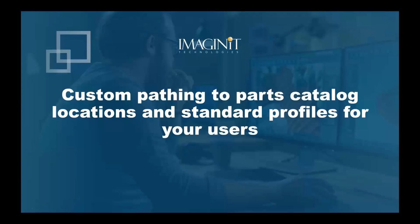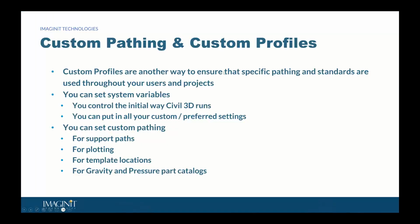All right, so now we're going to talk about custom pathing to part catalog locations and your standard profiles for your users. So custom pathing and custom profiles. Custom profiles are another way to ensure that specific pathing and standards are used throughout your users and projects. In the custom profile, i.e. an ARG file, you can set system variables, you control the way Civil 3D initially runs. You can put in all your custom preferred settings, all of your system variables, anything like that.